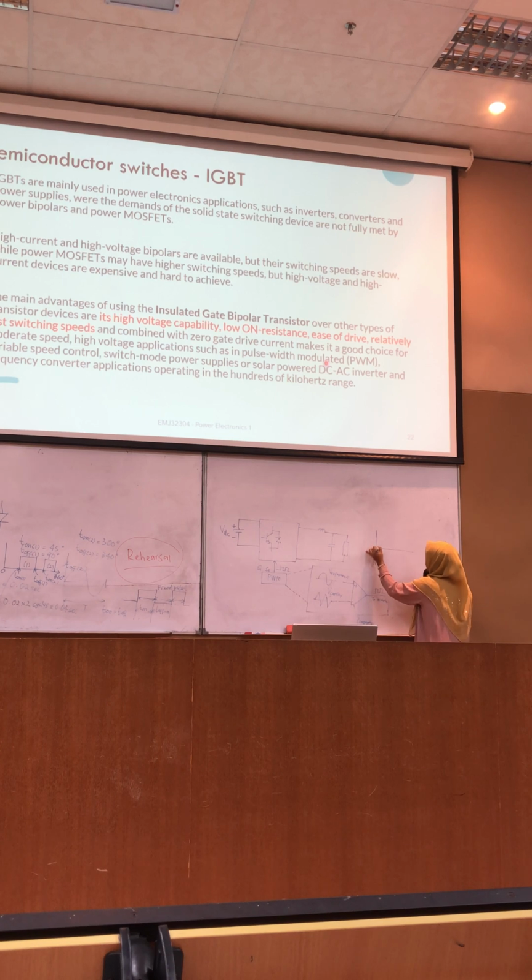So let's say you have a sine wave over here, and then you have your triangle wave, something like this. This is how it is compared inside this comparator. For each intersection point between the reference and the carrier, which is between the sine wave and your triangular wave, there will be an output. So there will be a pulse, whether it is 0 or 1.